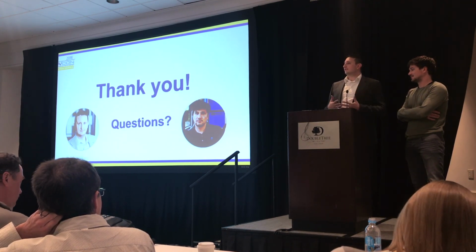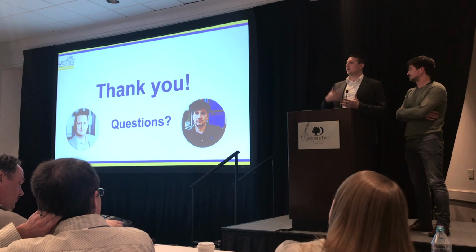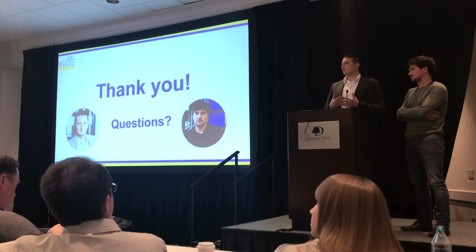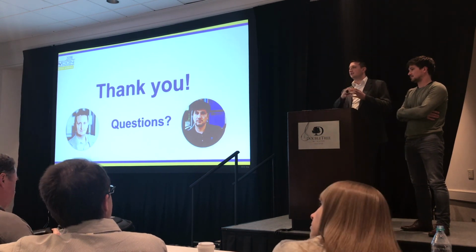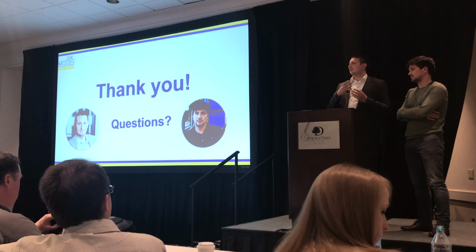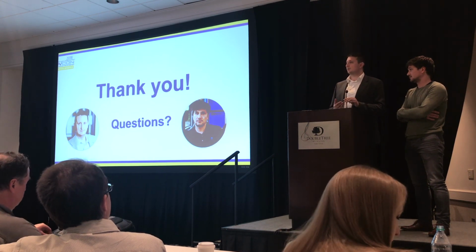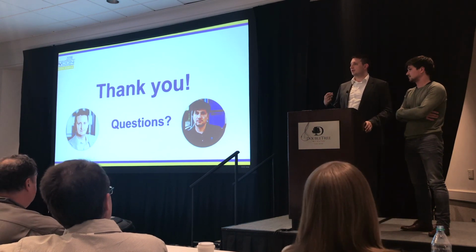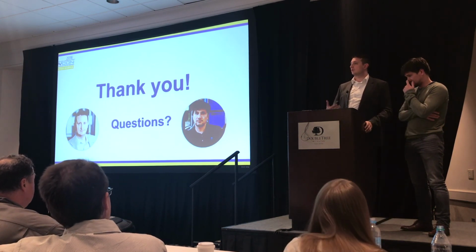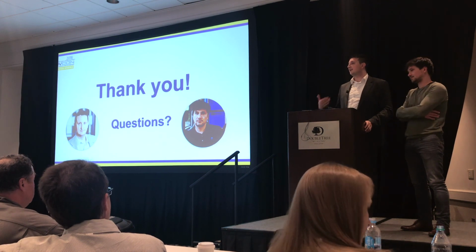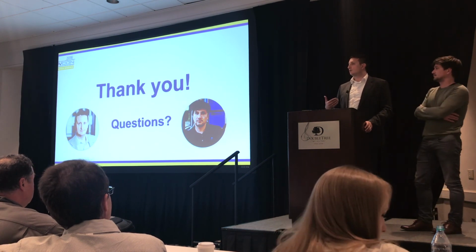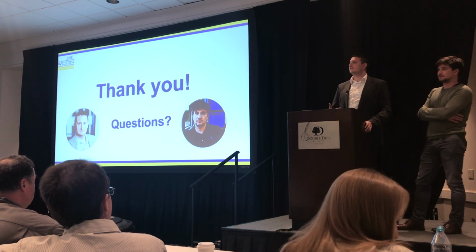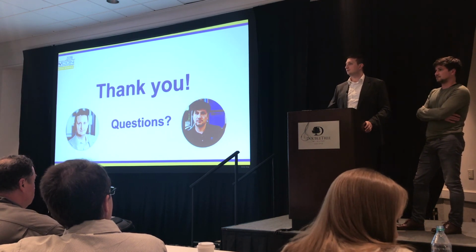So quantify actually observes the behavior of your code. The proof call will deal with the stimuli needed and the part of the design which is needed to prove the property, whereas we actually here measure the quality of the checkers. So if the checkers tell you that they're sensitive to a line of code and that the checkers would start failing if the line is different, I would put more trust and emphasis on that than on anything else. Okay.